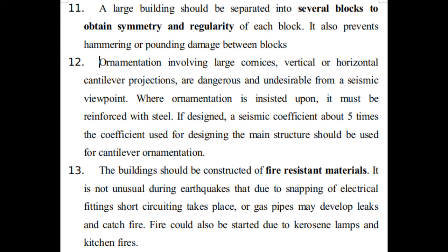Point number 12. Ornamentation involving large cornices, vertical or horizontal cantilever projections are dangerous and undesirable from a seismic viewpoint. So please keep it in mind. When ornamentation is insisted upon, that means you have to provide it from the architectural point of view, it must be reinforced with steel. If designed, a seismic coefficient about 5 times the coefficient used for designing the main structure should be used for cantilever ornamentation.